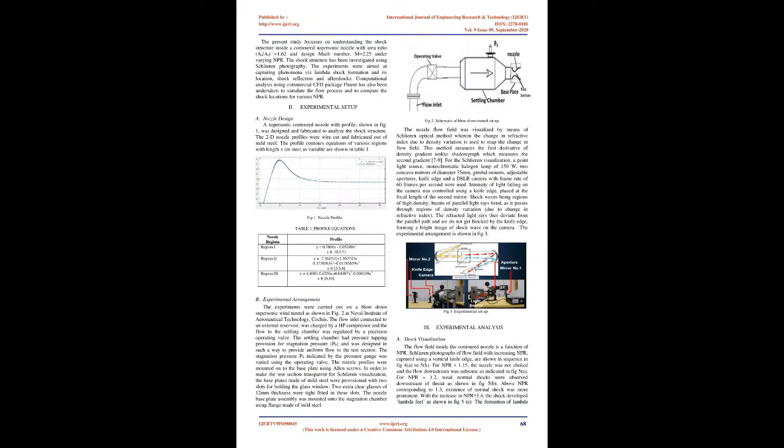The types of flow separation in rocket nozzles are categorized as free shock separation, FSS, wherein the flow downstream of the shock structure is detached from the nozzle wall and never attaches back, and restricted shock separation, RSS, in which flow downstream of the shock structure attaches back to the nozzle wall. The shock wave boundary layer interaction, SBLI, exhibits strong unsteadiness and unsymmetrical flow separation, leading to unsymmetrical circumferential pressure distribution on the nozzle walls, called side loads 4.